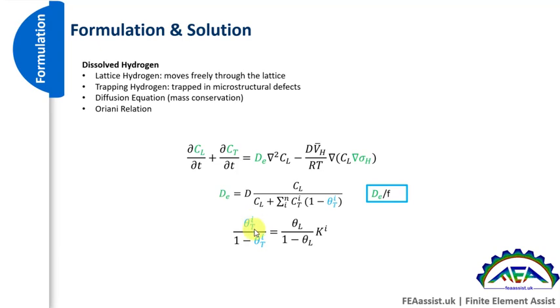It relates the trapping density to lattice sites. So we have lattice sites and a binding energy coefficient, and we can compute trapping site density, compute D_E, use D_E for safe and unsafe regimes, and then use D_E here to compute the hydrostatic stress from UMAT, and after that compute the hydrogen concentrations.